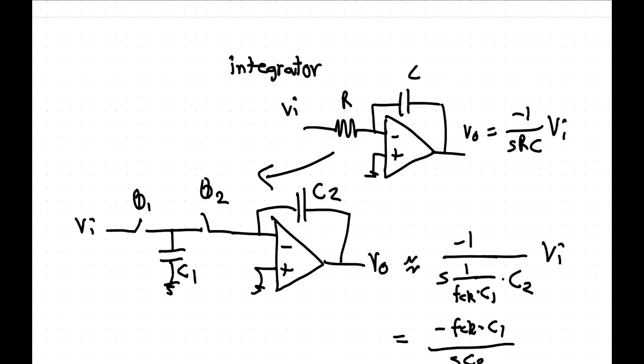Now if we got rid of this minus here, the only thing we did was change the resistance. So what happens now is that the resistance that we have is actually negative. If you have a voltage on the resistor, we get a current back to us. So that can be a bit tricky, because when you put this in a feedback loop, because you want to make a higher order filter, this is a negative resistor. So you've got to think about that.